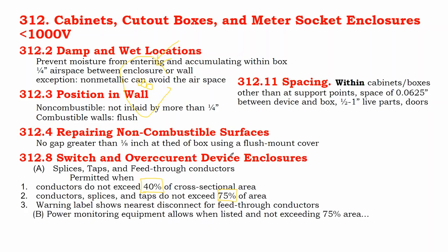We're going to see these requirements reappear in National Electric Code when it comes to what you can put in a box and what you can not put in a box. With smart homes, you sometimes want to put energy monitoring equipment inside an electrical box or an electrical service panel. Can I put this device inside my service panel?